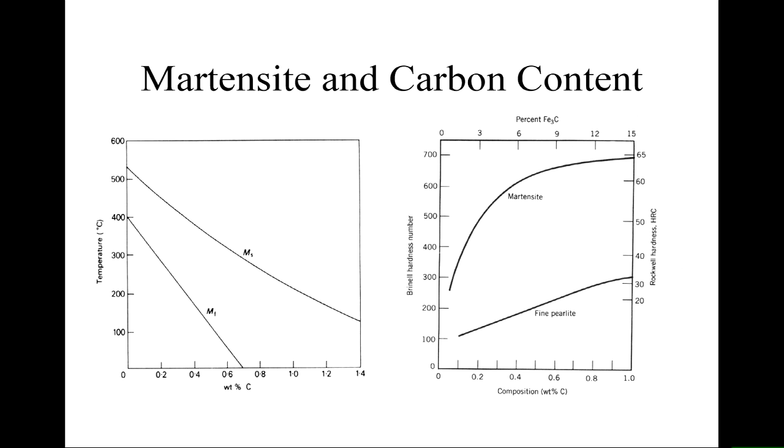So what does that mean in the structure? That means we started with austenite, we've converted some of it to martensite, but at these very high carbon contents, we can't convert some of the austenite. So we end up with austenite stable at room temperature called retained austenite. And you have those in gears and bearings and cutting tools. And if you want to get 100% martensite, you've got to stick this in a deep freeze. So there are heat treatment processes that involve deep freeze treatments or cryogenic treatments of the material to get 100% of this hard phase, if that's what you want.